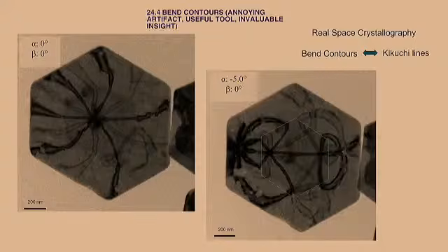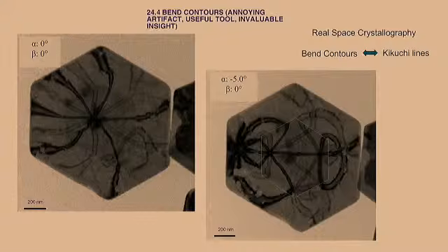Okay. If you look at the simple bright field image, I want to tell you that it's not always about atomic resolution. Even a simple, very innocuous looking bright field micrograph can give you so much detail. What we're seeing here are what are basically called bend contours. Any real material inside the microscope is getting bent, and therefore we have these bend contours. The really surprising thing is that the bend contours here are absolutely parallel to each other, which basically tells you that the bending that we have in this case is very uniform.